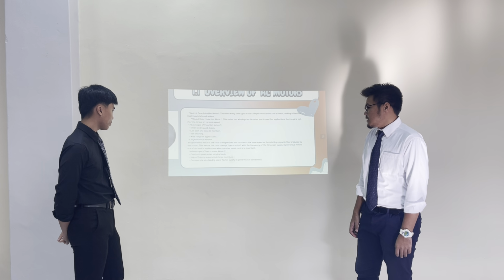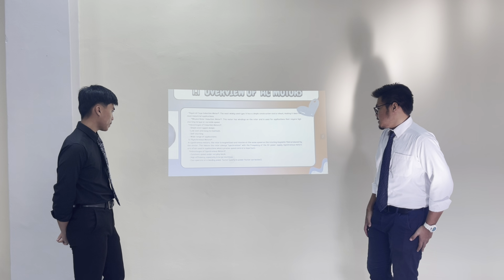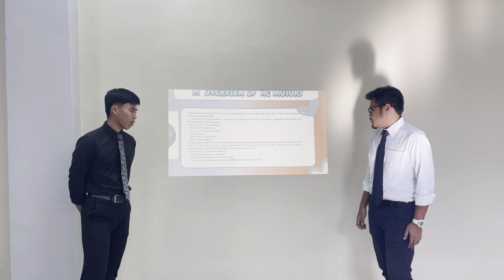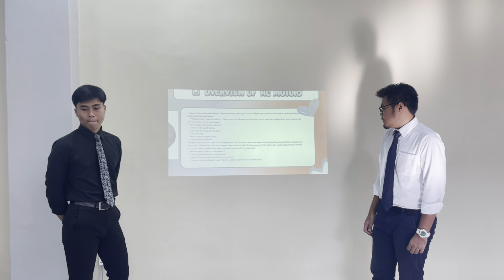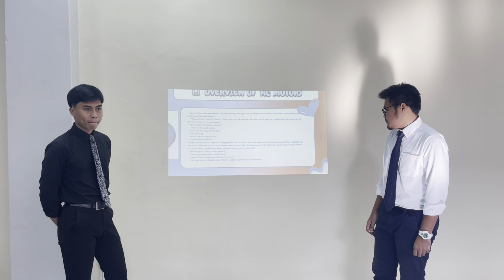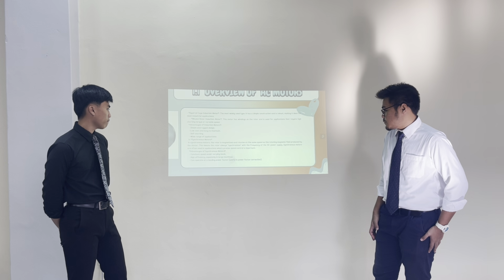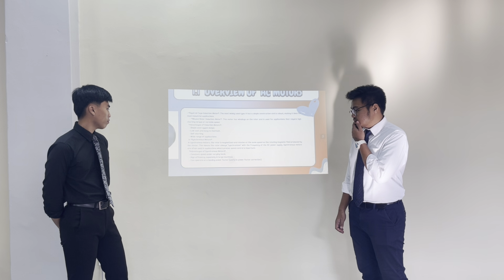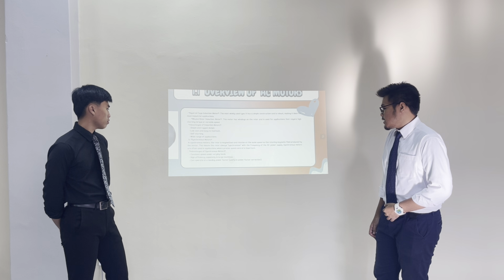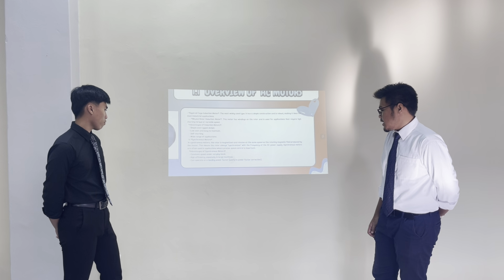Synchronous motor. In synchronous motors, the rotor is magnetized and rotates at the same speed as the rotating magnetic field produced by the stator. This means the rotor is always synchronized with the frequency of the AC power supply. Synchronous motors are often used in applications where precise speed control is important. Advantages of synchronous motors: constant speed under varying loads, high efficiency, especially in large machines, and they can operate at a leading power factor, used in power factor correction.